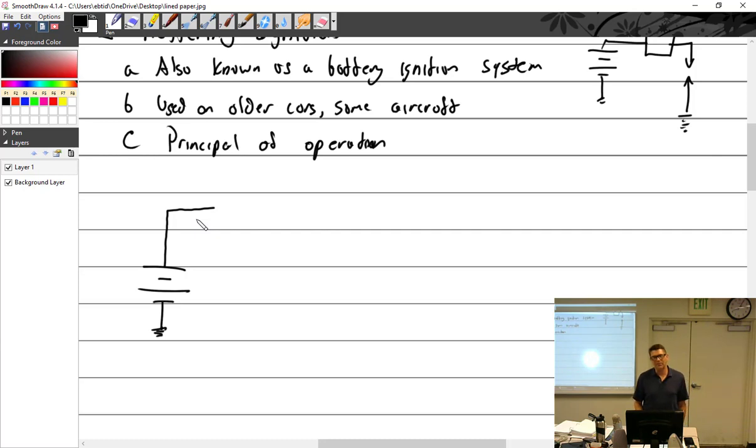So anyway, I'm thinking about that, and in order to utilize the Spark Advance, you turn off one of your magnetos, which there goes your efficiency. But they claim that it's more efficient and more powerful. So I don't know. You do with that what you want. I think the best of both worlds would be if they somehow could take that electronic ignition and fire all the plugs with a magneto backup. I don't know. Probably just the battery backup's the way to go.